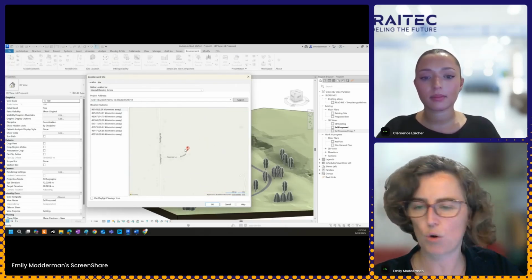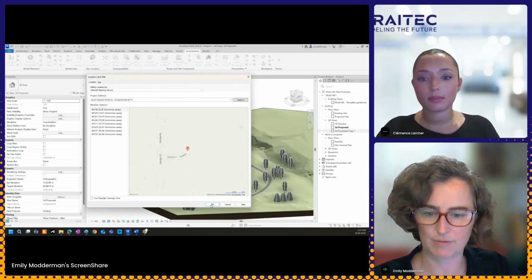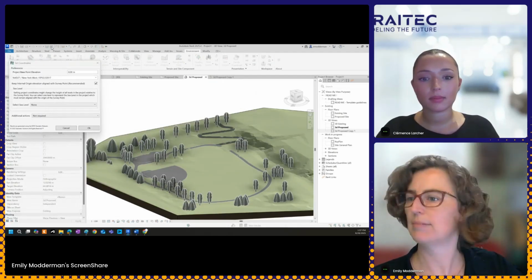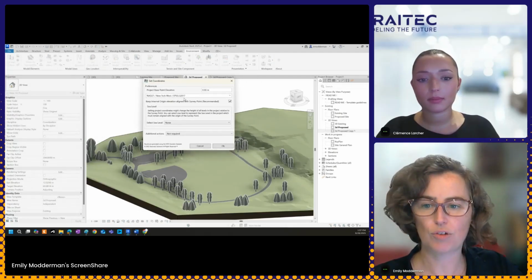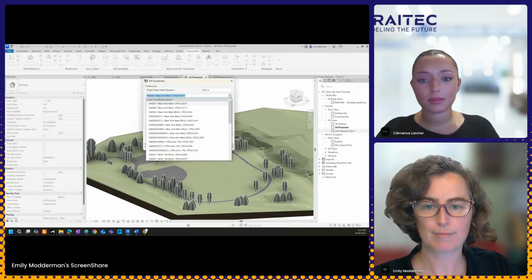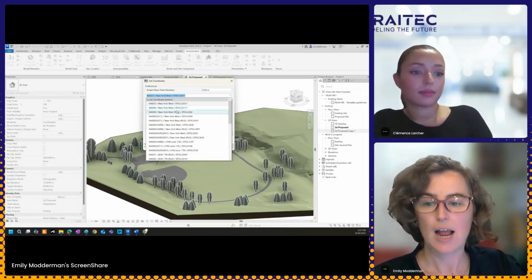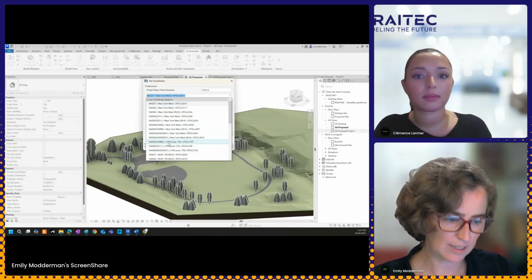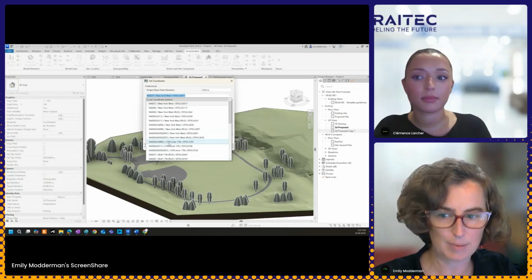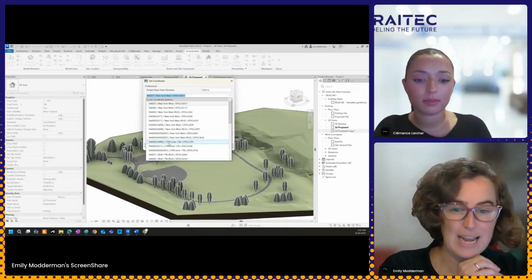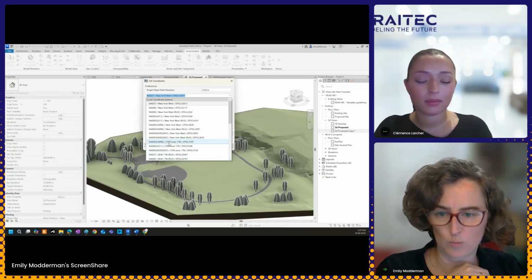Okay, and I can put that at the corner or generally at my site information. And then, there it is, I can choose the local coordinate system. That's what I was missing. So I can choose that local coordinate system, and when I can get that set up at the beginning of a civil file, we can get that information in Revit as well.